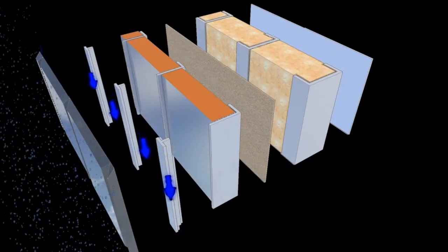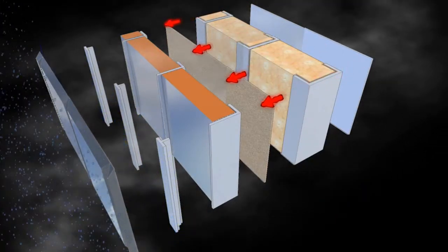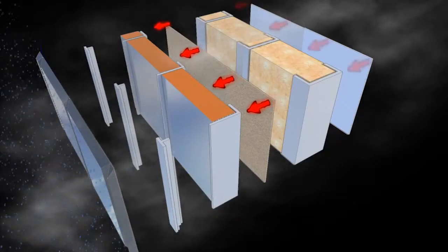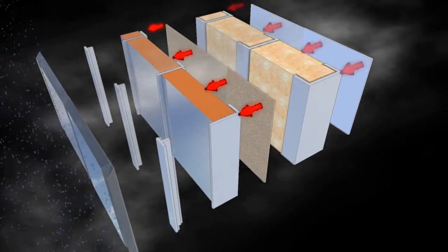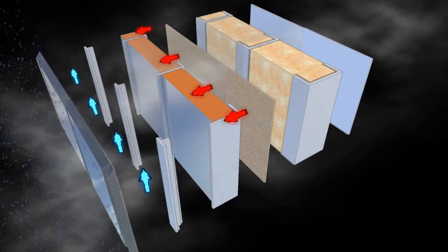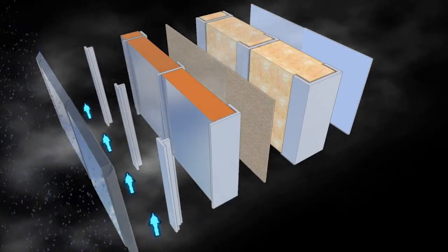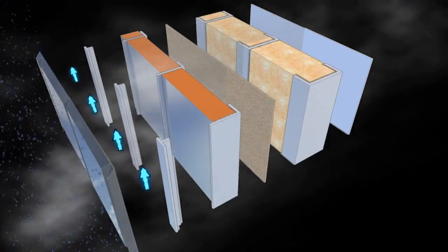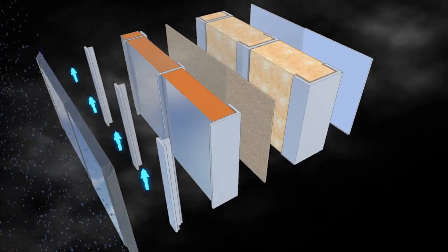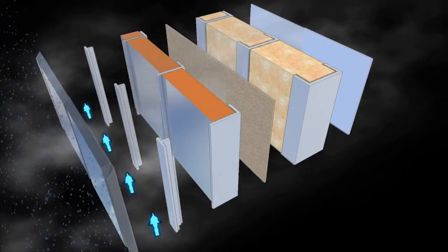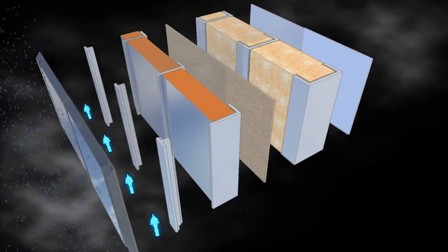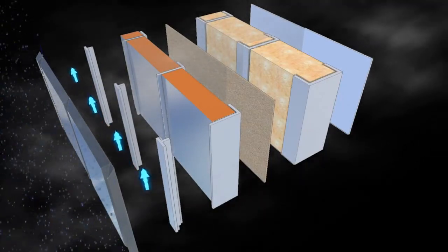As well as for allowing for the drainage of liquid water, rain screens should be designed to ensure moisture from the interior of the building can escape and that any wetting associated with water ingress through the outer rain screen can dry out. This is typically achieved by fully ventilating the void between the outer cladding panels and the inner leaves of the wall. By ventilating, we ensure moisture vapour from all sources can escape freely to the outside. However, it does also mean that achieving a good airtight seal of the inner leaf is critical to minimise air leakage. A well-designed weather-tight layer is only as good as its durability, and a carefully designed rain screen that cannot resist damage will be limited in its usefulness.